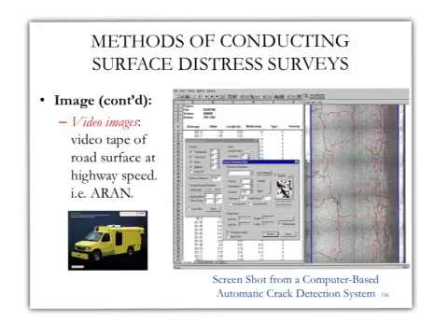And then you would see that all this information is now being plotted already, and even the cracks, as you would see here, are already identified. So this is simply a screenshot of the computer-based automated crack detection system. So you don't even have to sit down and try to identify. The software itself would detect the type of crack and the width and the severity. As you could see here, this is a close-up picture of one of the cracks, and based again on the difference in coloring, this is also how it identifies the width and the extent of the crack.